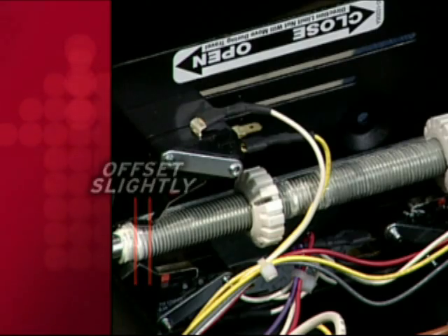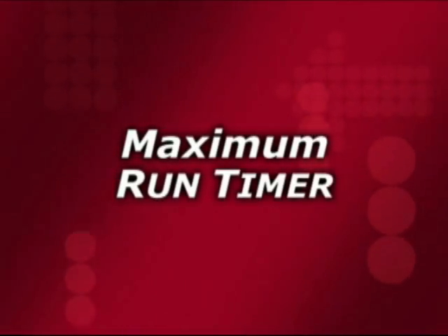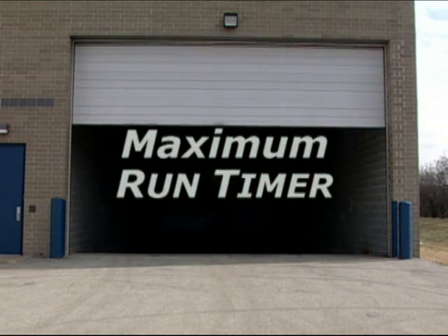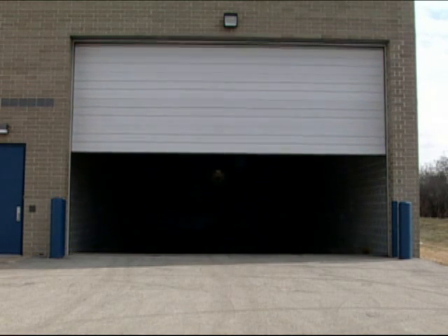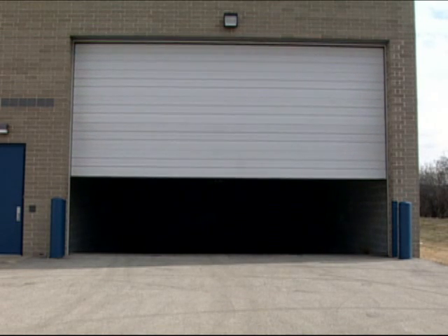The maximum run timer feature on the Logic 3.0 control board signals the door to stop if the door's opening or closing time exceeds the normal run time by more than 10 seconds. This feature protects the door and operator from major damage. Simply set the system to auto-learn the door's standard cycle time. Anytime a closing door takes 10 seconds or more than its programmed standard cycle time, the door will stop. The factory default for the maximum run timer is 90 seconds.